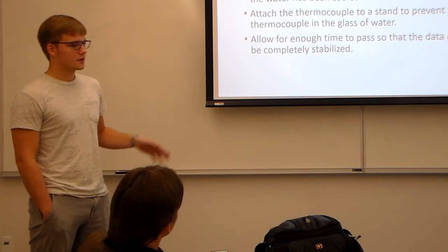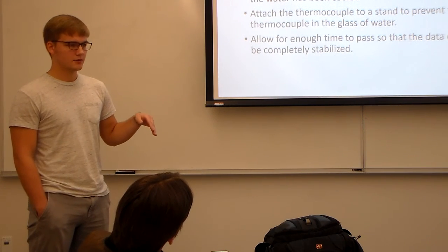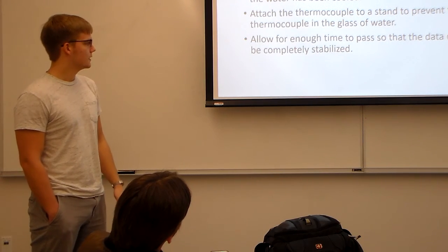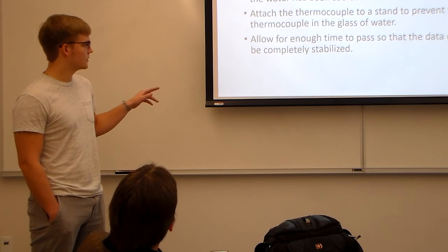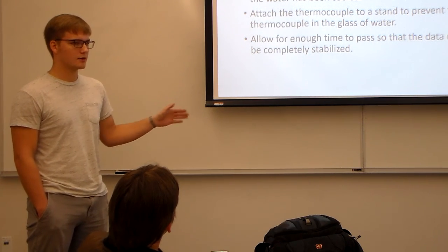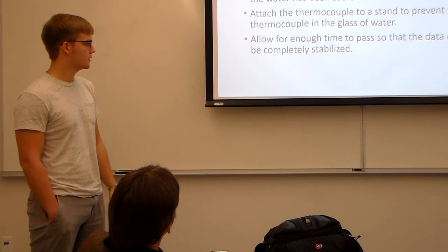We could also make sure that we attach the thermocouple to a stand, preventing human error from the thermocouple moving and possibly hitting the walls. And then I feel like also we needed to wait longer before taking the thermocouple out of the water to make sure that we got a full set of data rather than just a partial set of data.